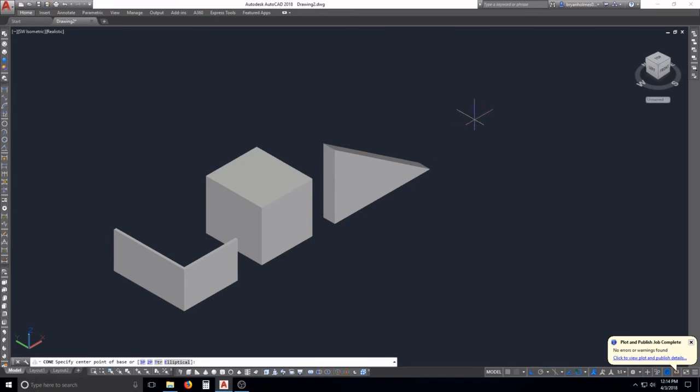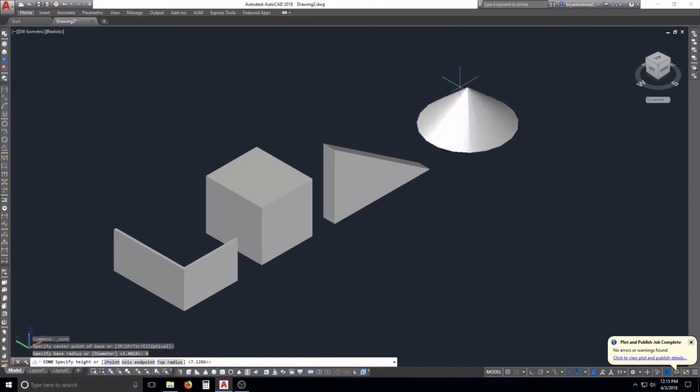So that was out. Now is a cone. Again, just left click. This is going to be about a radius point. So see how I went from the center of the circle and then out. And you can actually see the ortho giving the total distance out we want to go. And if you just type in what you want, say 5. No, let's back up. Say 4. See, we're already at 4.23. So we typed in 4, enter, and it'll lock in that 4. And then now you can pull up. And then you left click when you're happy. There you go.